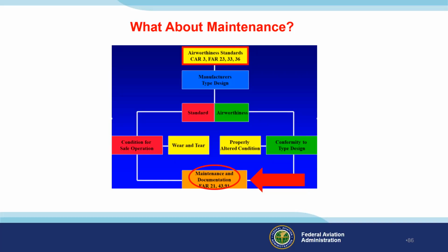Nobody will know if the aircraft was inspected or a repair action was accomplished after it's done. You can't tell if you repaired the internal workings of an engine just by looking at it. That's why it must be recorded in the maintenance log, and if it's not recorded, you have no proof it was accomplished. This is why the FAA makes falsification of records a very serious offense.